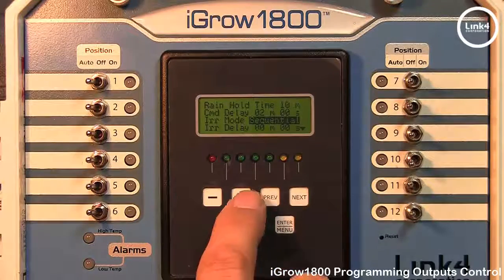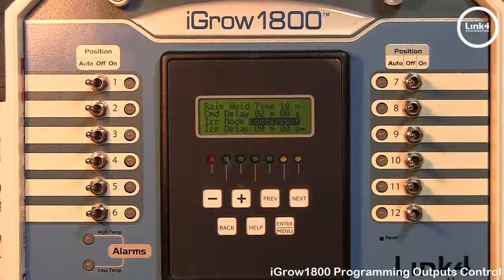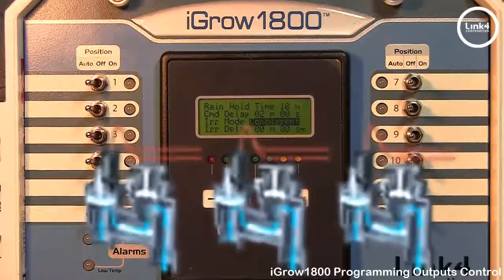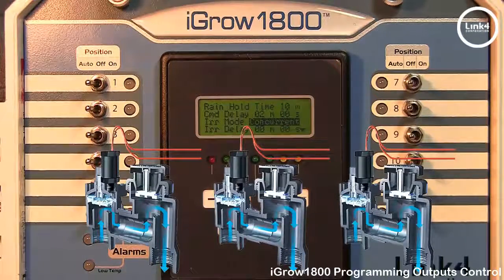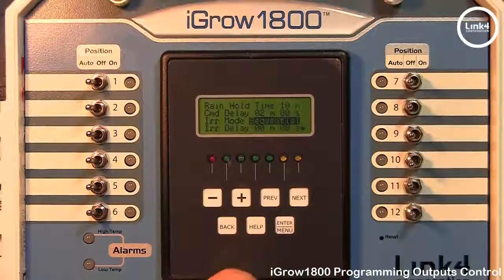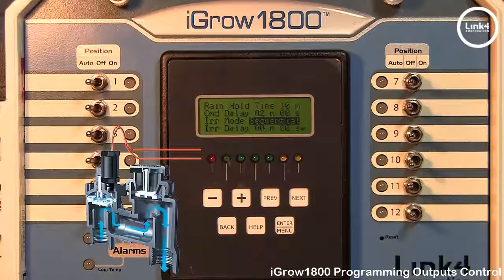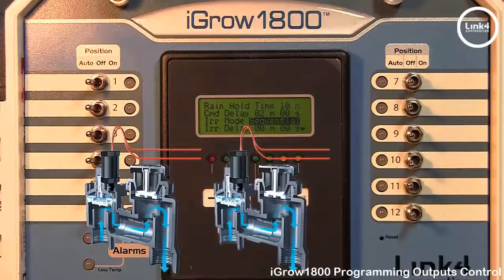Now if you select concurrent, then the valves will turn on immediately when requested, regardless of how many are already on. If you select sequential, then the first one will turn on, but if other valves are to come on, they will wait in queue and each one will come on in succession.